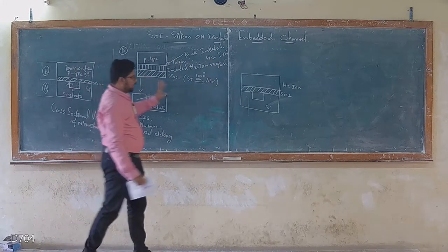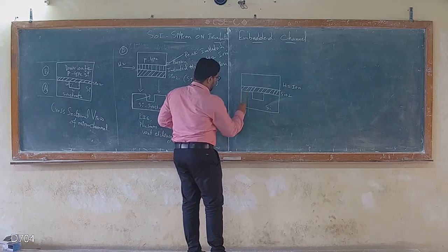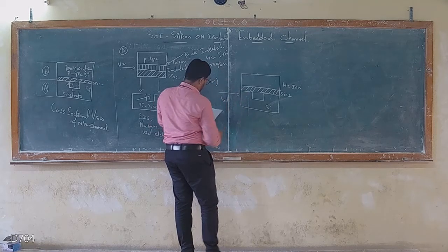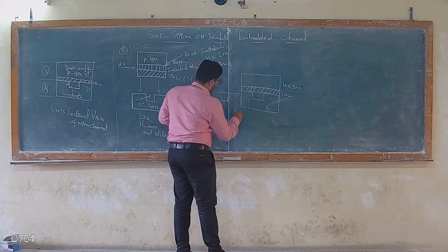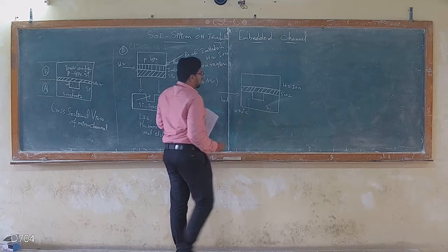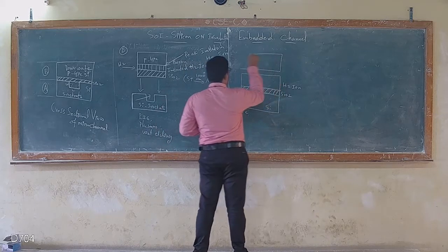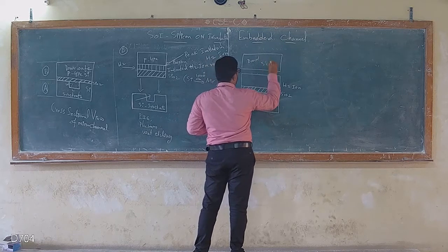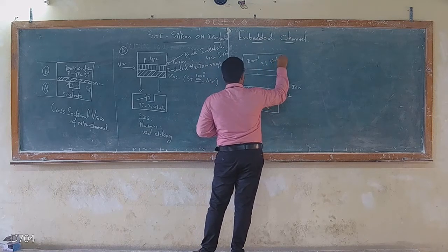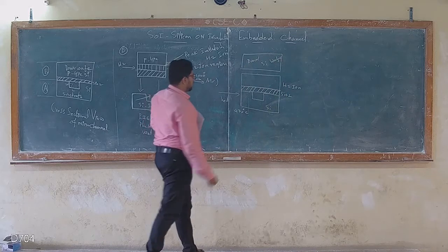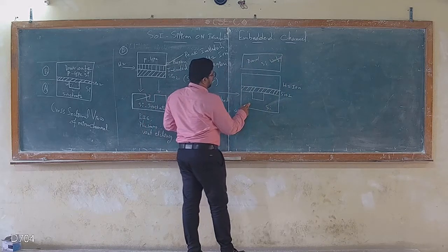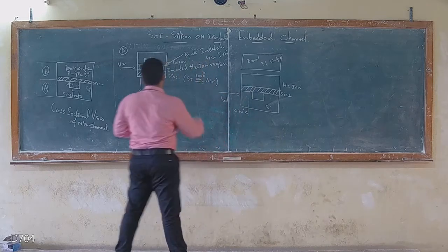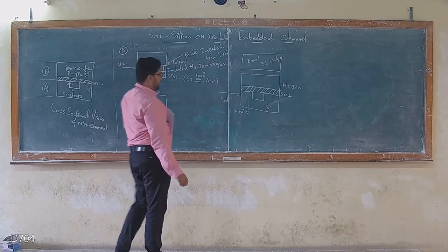So what happens after this? I'm going to apply some heat, around 470 degrees, because I have to remove the donor Si wafer. This is the acceptor Si wafer, and above it we have the H2 ion Si wafer. I want to remove these two portions by applying heat.